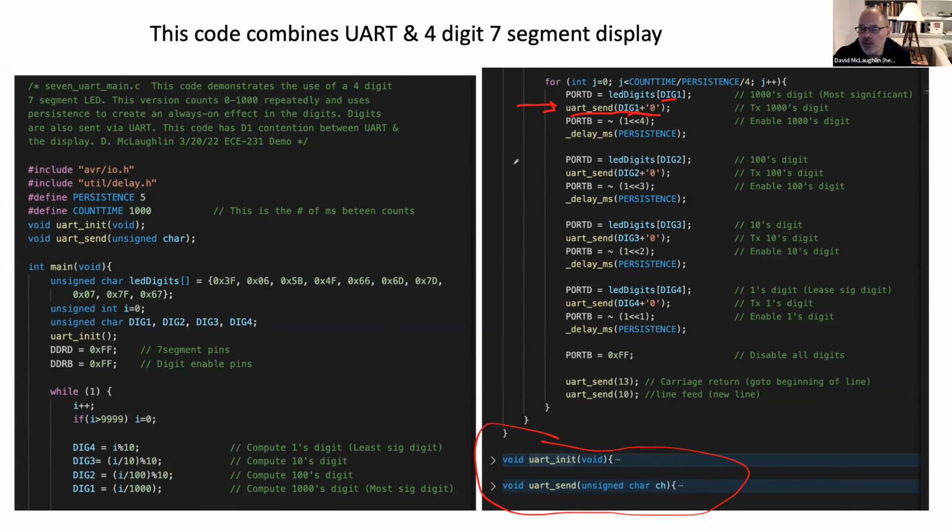I'll run this again, and I want you to just keep an eye on that segment. I'm jostling the camera, but this circle will settle over to that pin. Take a look, 4, 5, pin segment B is coming on when it shouldn't be coming on.